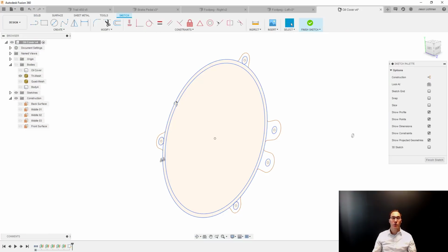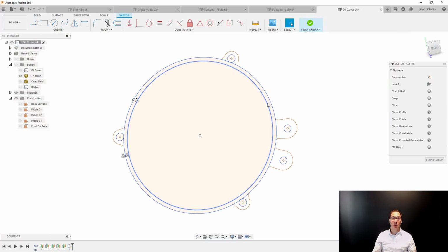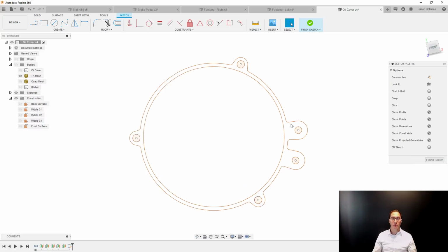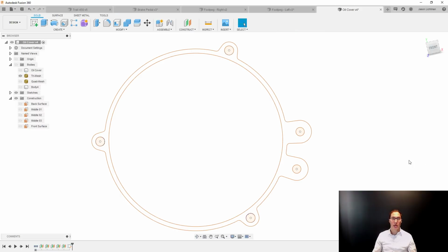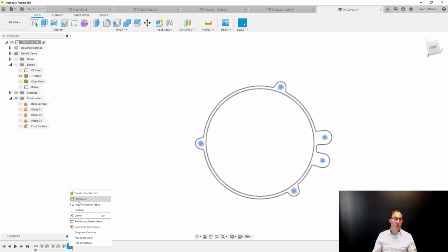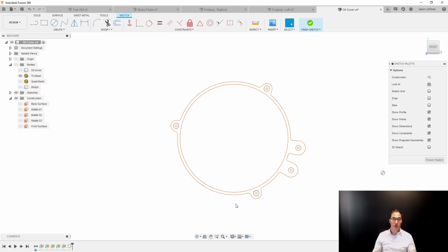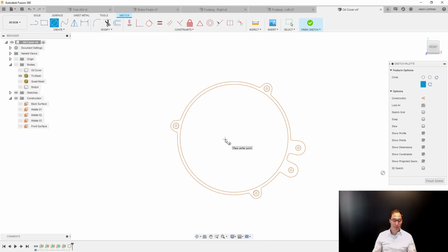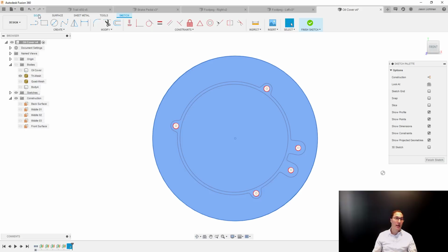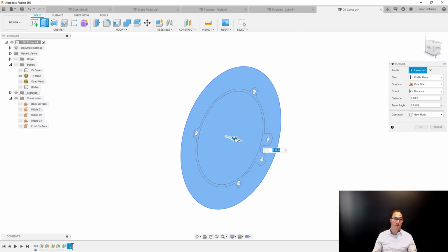So if we go back to our oil cover, maybe I don't want to reverse engineer anything related to that. All I care about are those holes. I've just reverse engineered those hole positions. Now I have that in a sketch. I could actually go and create a totally new sketch of a totally different part that I want to create that maybe is just going to use those holes. So now I could go and take just this shape and solid model that.